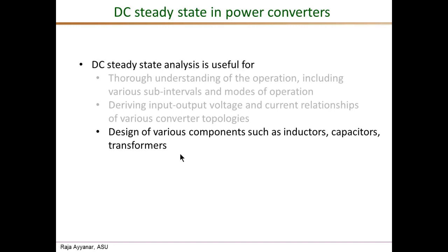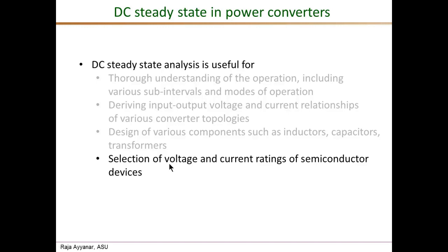Then the design of various components, particularly the filter components such as inductors and capacitors, and if it is an isolated DC-DC converter, the design of transformers, all of those are facilitated by a thorough DC steady-state analysis. And even the selection of the voltage and current ratings of the various power semiconductor devices like the MOSFETs and diodes is also done by doing a steady-state analysis.